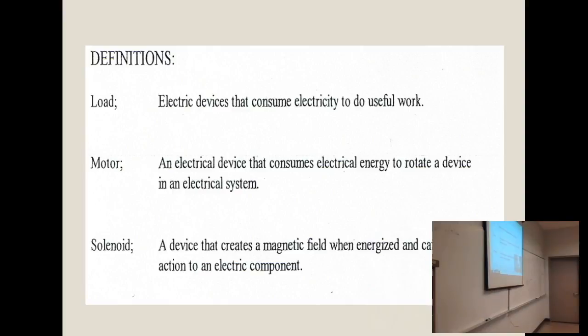That's considered pretty cheap. Not to mention, with contactors, when you have a voltage problem on the 24 volts and the coil starts losing power, a lot of times it'll chatter, and that's a lot of noise in the ductwork. So using a sequencer is the best choice, okay?